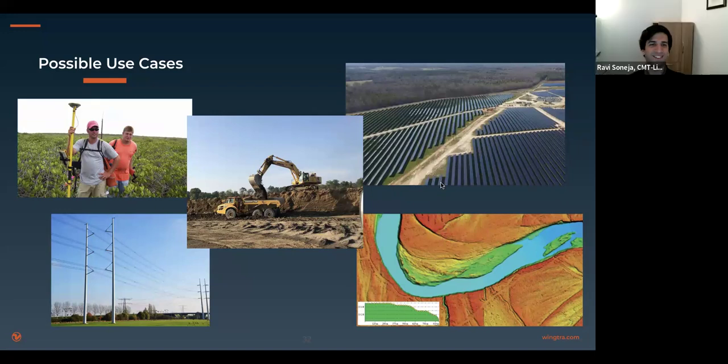Oh, I think I saw that question. Yeah, I'm not really sure if it would work for detecting very small holes in the ground. But there are some things you have to keep in mind with mapping through vegetation. If it's very dense, thick, matted grass, something like you'd find in a marsh environment, realistically, you're probably going to end up mapping the top of that grass, if it's that dense.